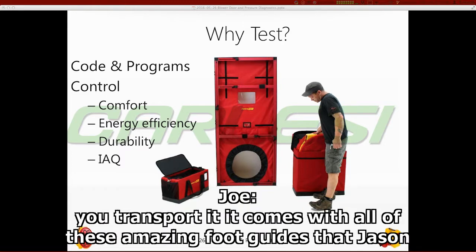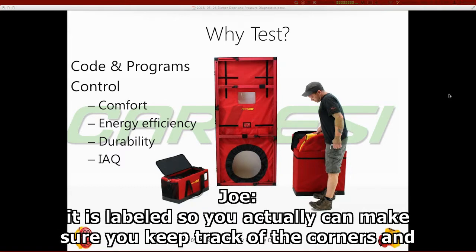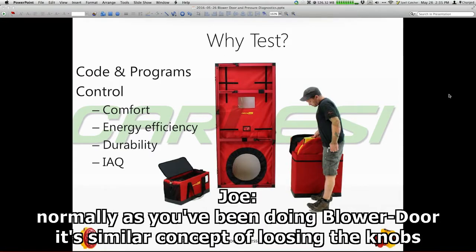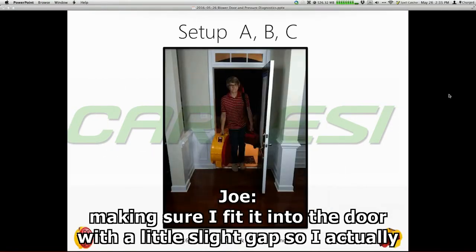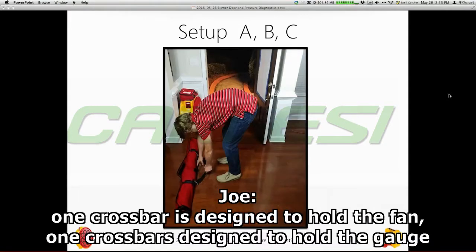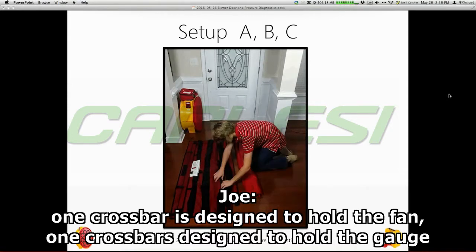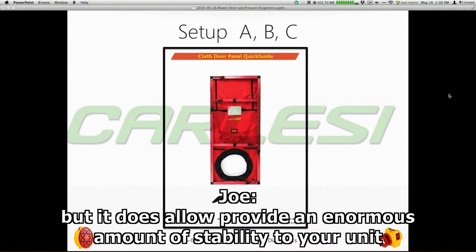So that's the cloth panel and how you transport it. It comes with all of these amazing quick guides that Jay's been mentioning, and here's how simply the frame snaps together. It is labeled so you can keep track of the corners. As you've been doing with blower doors, it's a similar concept: loosening the knobs and fitting it into the door with a slight gap so I have room to come back. When I put it in with the cloth, you get two crossbars. One crossbar is designed to hold the fan, one to hold the gauge, and they provide an enormous amount of stability to your unit.